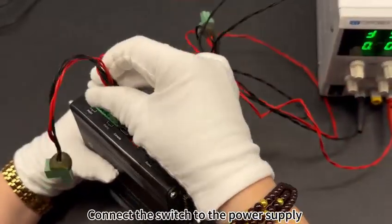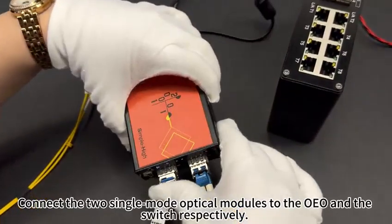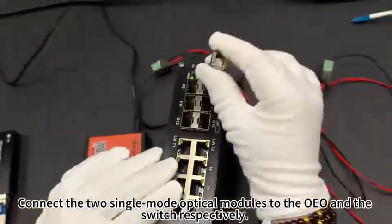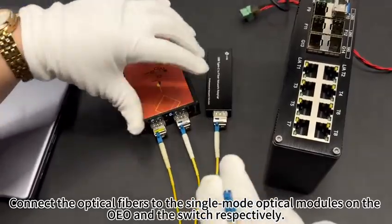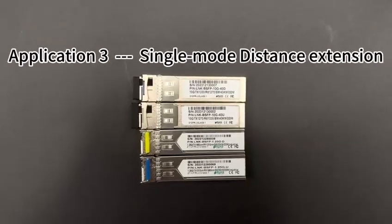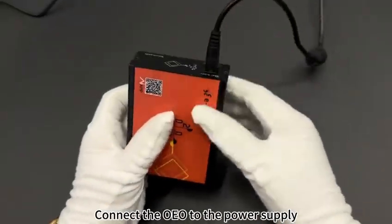Connect the switch to the power supply. Connect the two single-mode optical modules to the OEO and the switch respectively. Connect the optical fibers to the single-mode optical modules on the OEO and the switches respectively. Connect the OEO to the power supply.